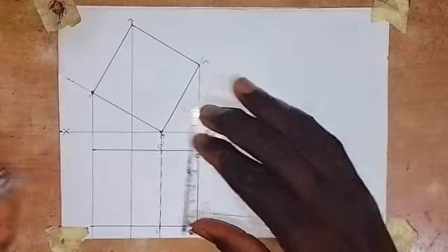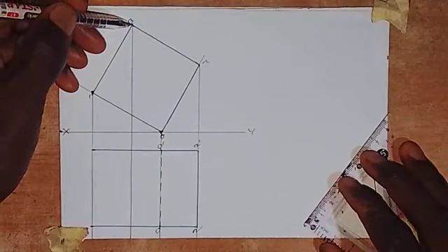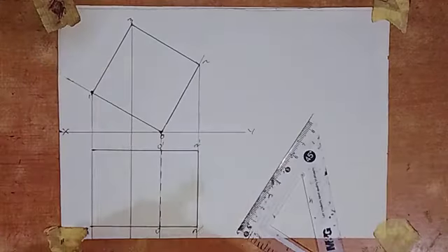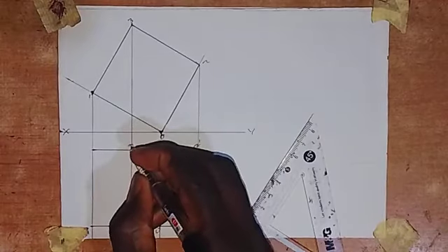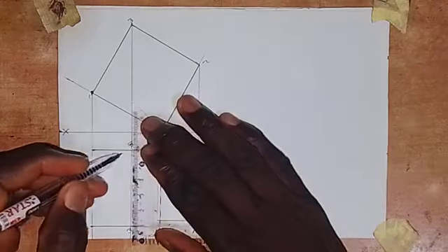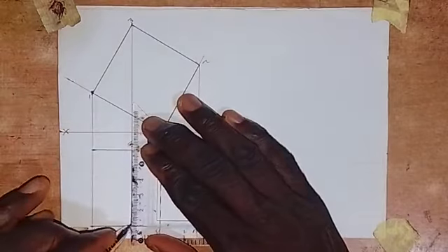All right, so we have this, and then I will also see a line as an edge of the cube at this point. So we are going to have this to be point 3, and this will be point 3 prime. So this will be 3 prime. Okay, we have this, and that line will be visible to me. So I have to make this a thick line from here to here.